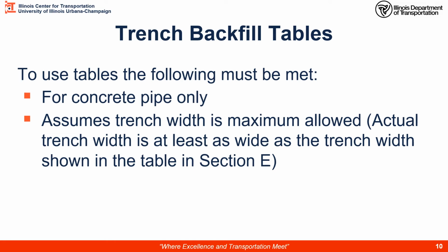Let's talk a little bit about trench backfill. In your documentation guide, in section E, E is in Everett, you will find a series of trench backfill tables. These are very handy to use. They're for concrete pipe, so they only work for concrete pipe because the wall thickness is taken into account in these tables.